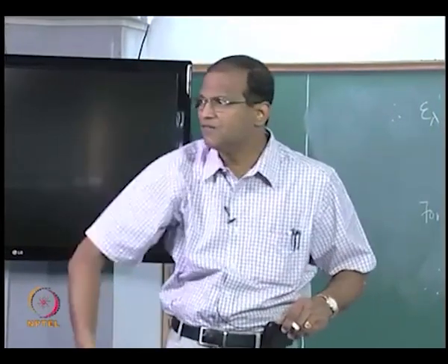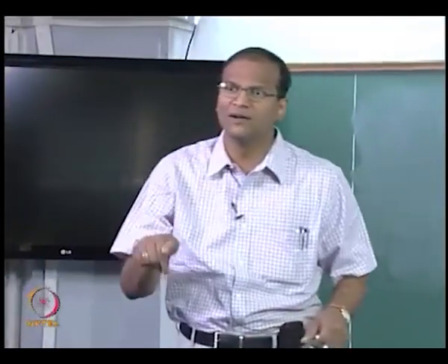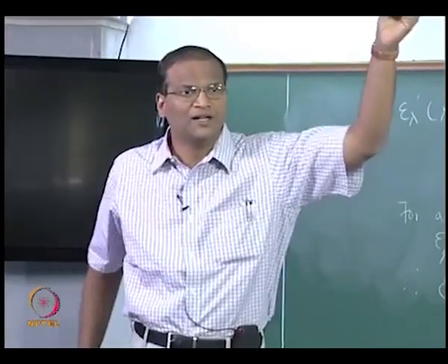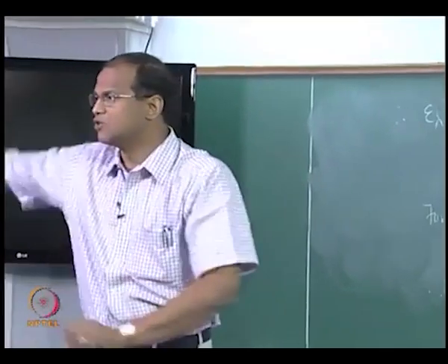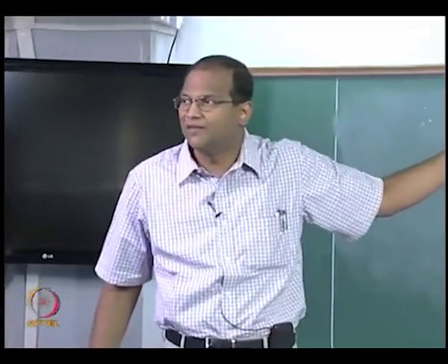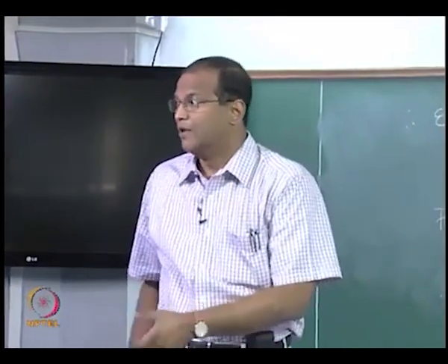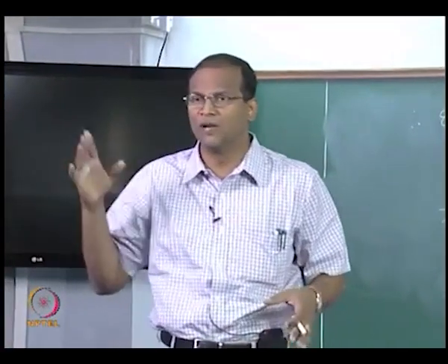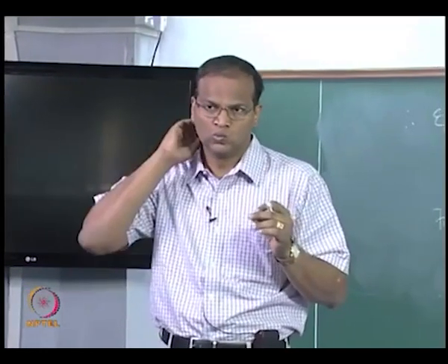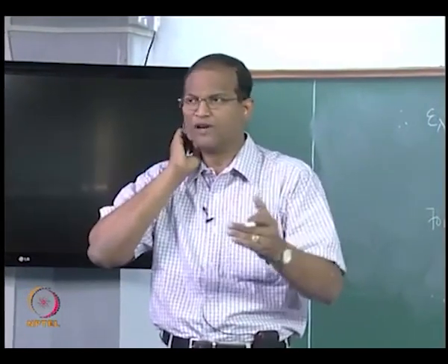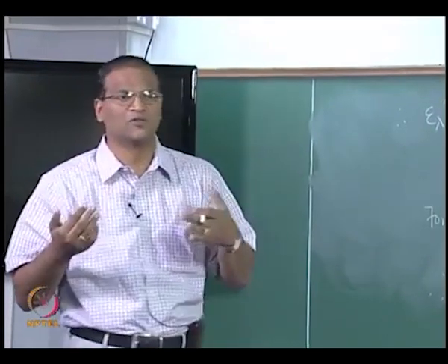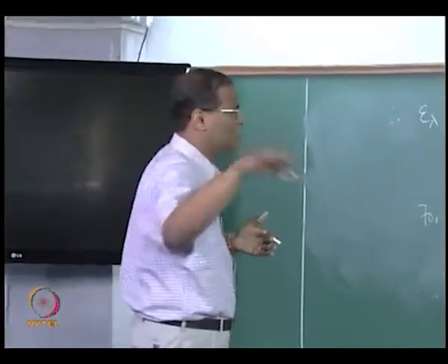The incident radiation can be in one direction and the reflection can be in all directions, it can be diffuse, or it can be specular, that means it is entering in one direction, it is going in one direction only. That is why for absorptivity we use I with respect to theta I phi I, but reflectivity will have theta r phi r, it will complicate. Reflectivity is one of the most complicated things. And it is the most fundamental property. Okay, so I will tell you what are the complications associated with reflectivity in tomorrow's class or next week's class.